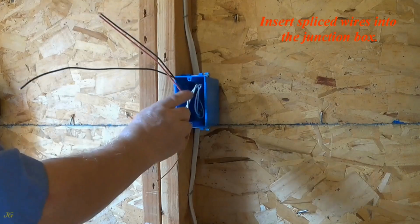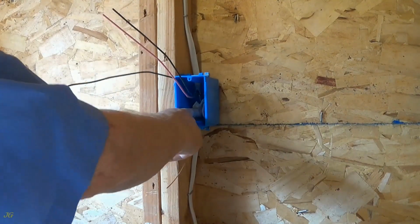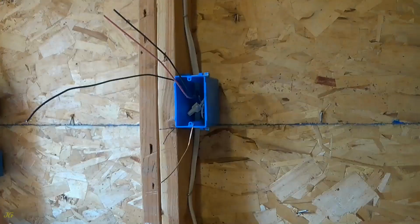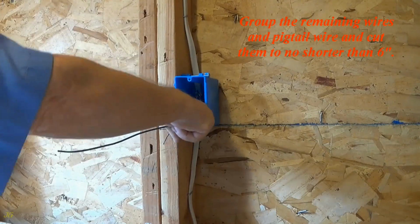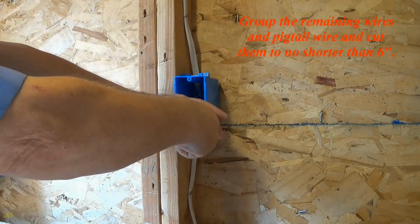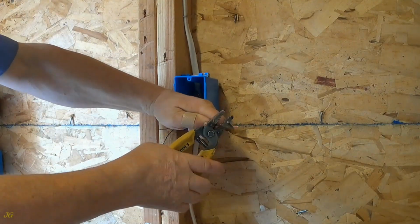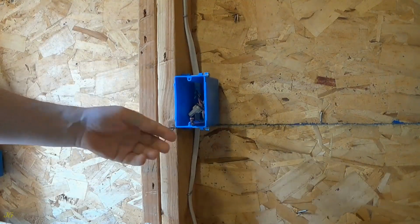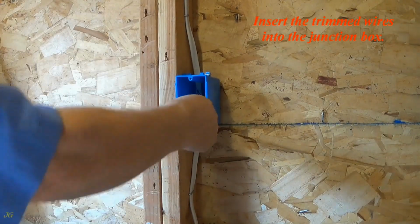Insert spliced wires into the junction box. Group the remaining wires and pigtail wire and cut them to no shorter than 6 inches. Insert the trimmed wires into the junction box.